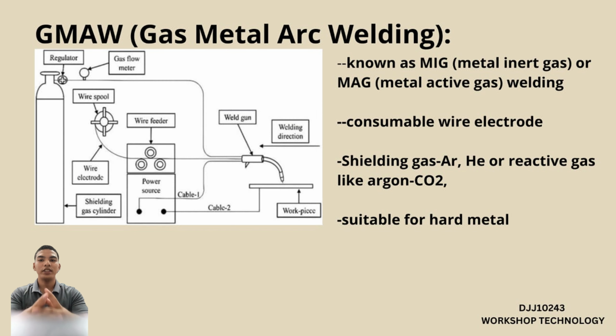For your information, GMAW is also known as MIG welding. MIG welding is a semi-automatic arc welding process that uses a continuously fed wire electrode and shielding gas to join metal. An electric arc forms between the consumable wire and the base metal, melting both and fusing them together, while the shielding gas protects the molten weld pool from atmospheric contamination.